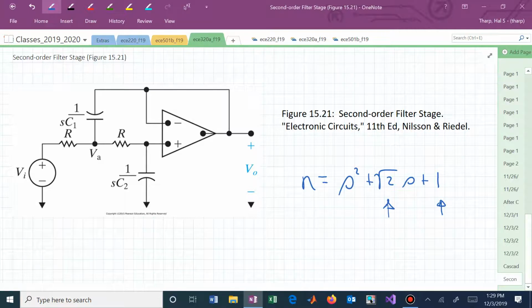You say, yes, but Josie just gave me 10 microfarad capacitors. Then you magnitude scale so that your final value of capacitor is 10 microfarad, and you figure out what is my magnitude scaling factor, K sub m. Oh, now I need to scale my resistors to be consistent with those capacitor values.